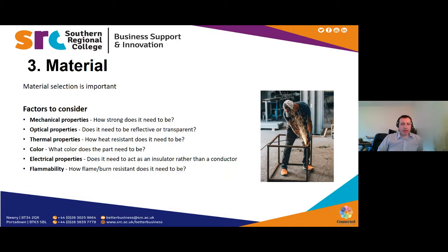Originally, we designed this using a heavier wall box section, but after carrying out an analysis in SolidWorks, we realized we were going too thick. So we were able to reduce the thickness of the box section by half. This meant less time to weld it, it was easier to maneuver around the workshop and fabricate, and it was easier for the farmer or contractor to operate. As well as that, less galvanizing was required, so there's a saving there as well.